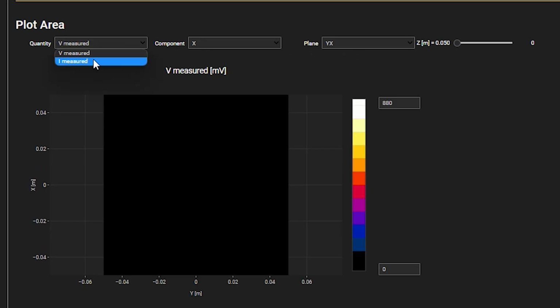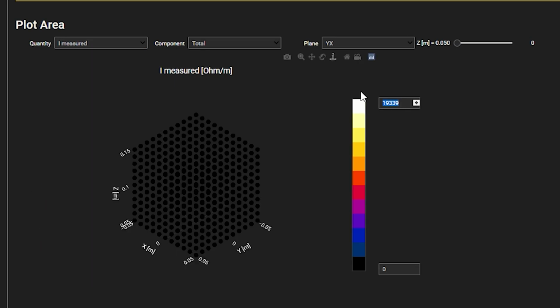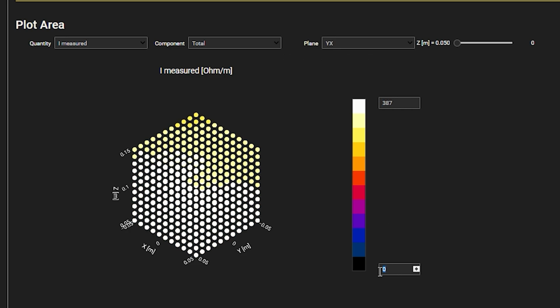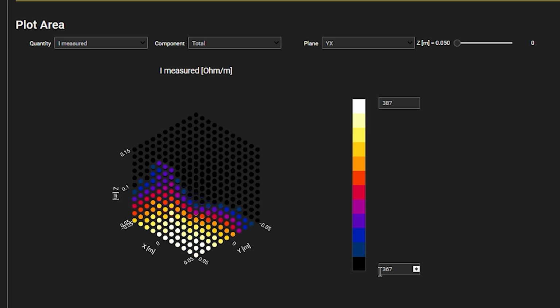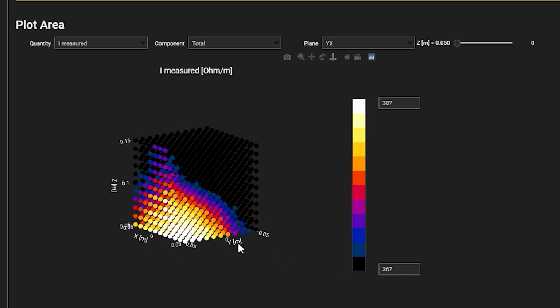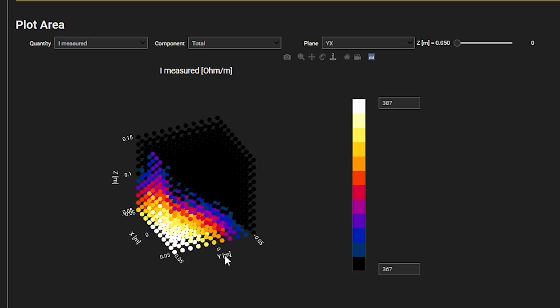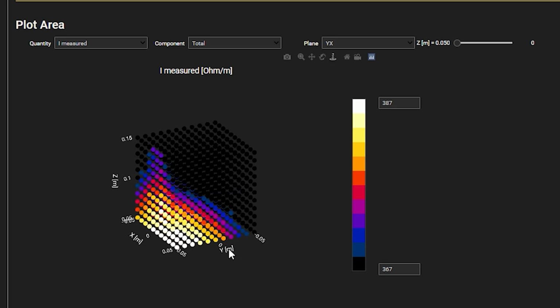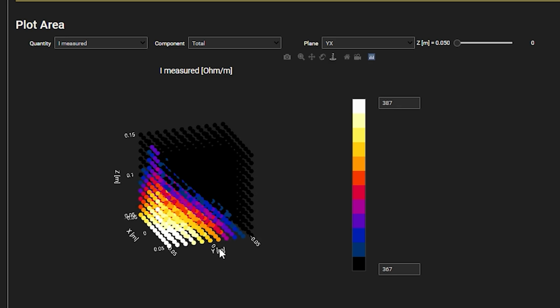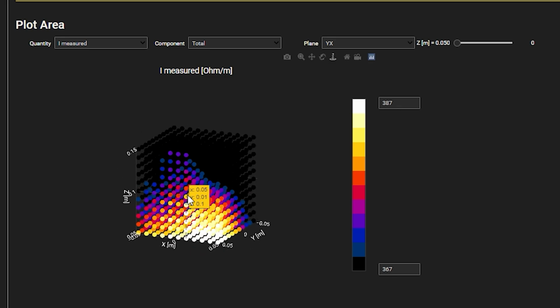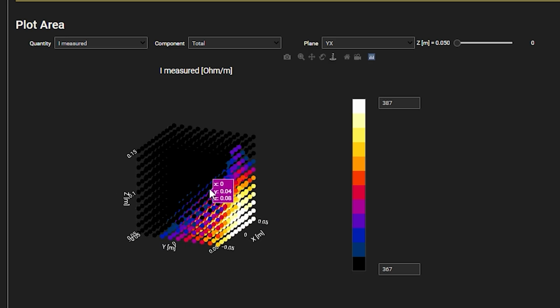The impedance plot shows 377 plus minus 10 ohms in a relatively large volume of almost 40 by 40 by 40 millimeters in the center of the TEM cell that I can use as my calibration volume. The fields are poorly defined close to the opening, as expected. The procedure is indeed easy and straightforward.